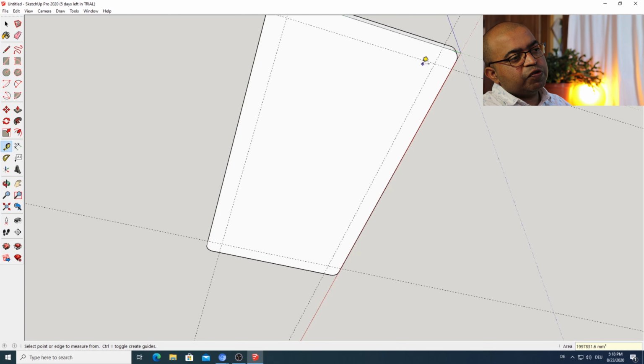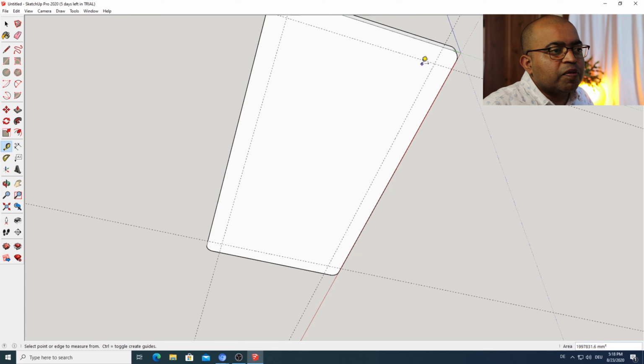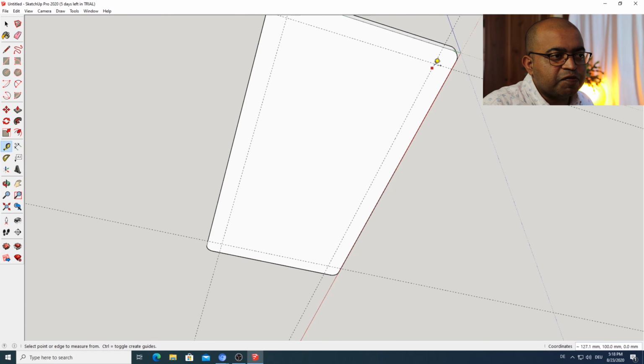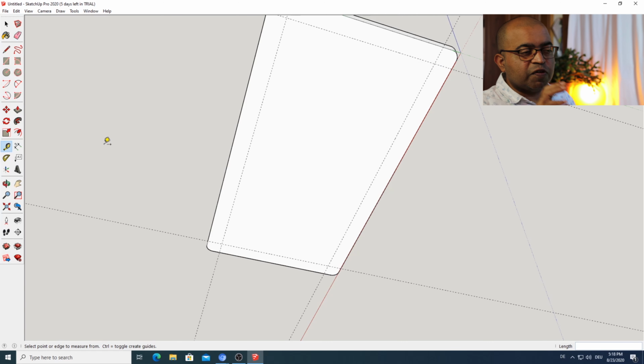Now what I want to create is a leg. So once again, here we are creating the legs of tables, and what I did was I've created construction lines to show where each of the legs should be placed. Using the rectangle tool, I've created a square cross section, 5 centimeter by 5 centimeter.